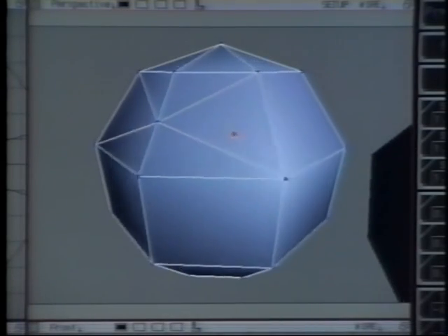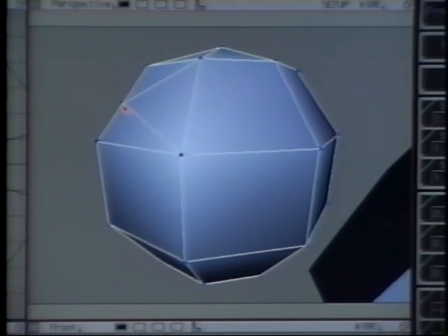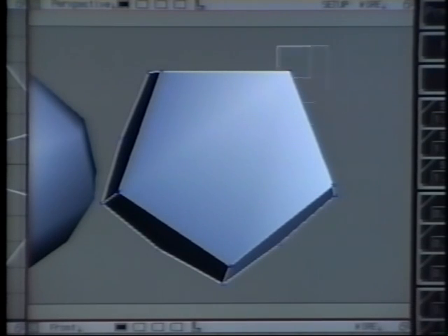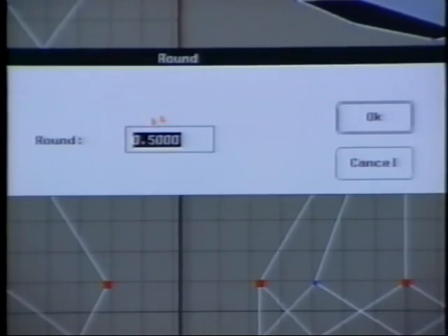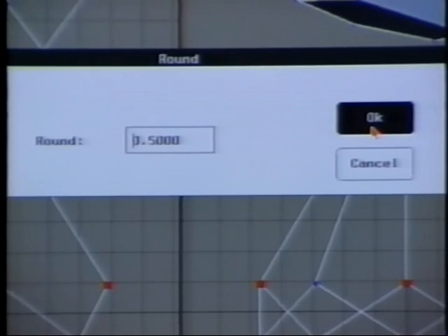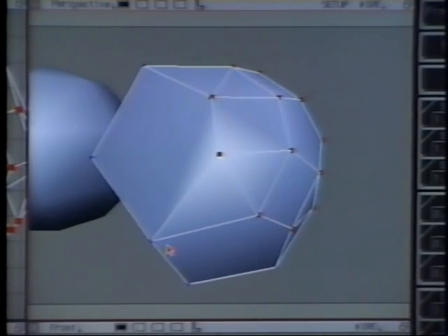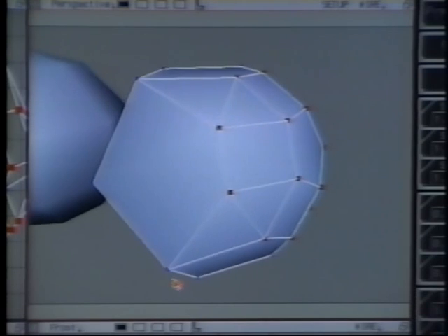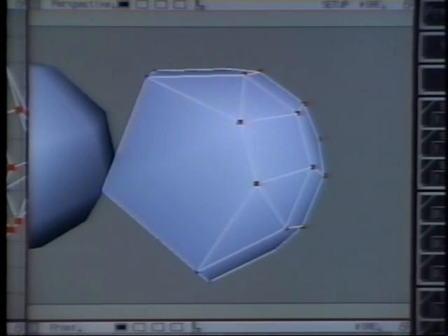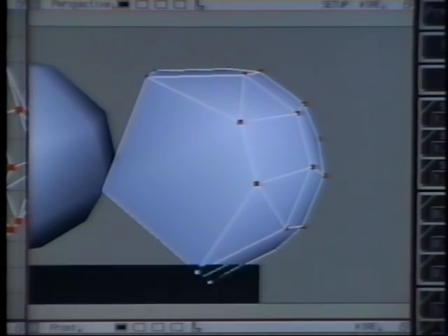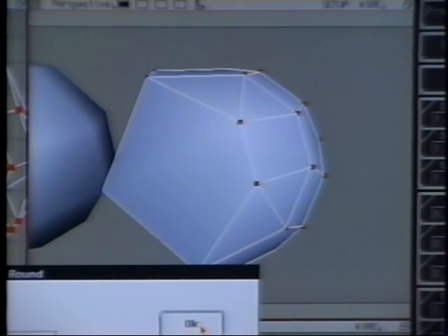In polygon edge mode, we can add edges connecting the new points and then move a point to add a local detail. We can also tag several vertices at once and add more points to the entire tagged area while we're in tag mode by selecting Effect Rounding. Effect Rounding can give one specific subregion of the mesh a higher resolution than the rest of the object, and can create much denser subregions if the command is used more than once.